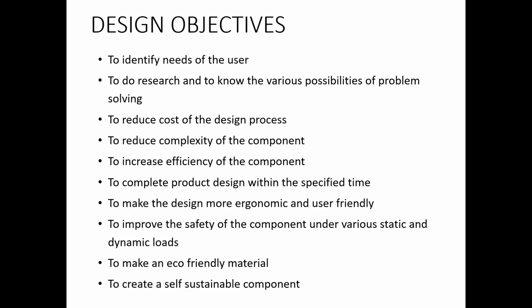Reduce the complexity of the component. So whenever we are simplifying the design, the component geometry and the shape etc. becomes much simpler, easier to produce. So always one objective for the design team should be to reduce the complexity of the component, the number of parts that make up the component if it is an assembly. So try to minimize the complexity for designing and making that component.